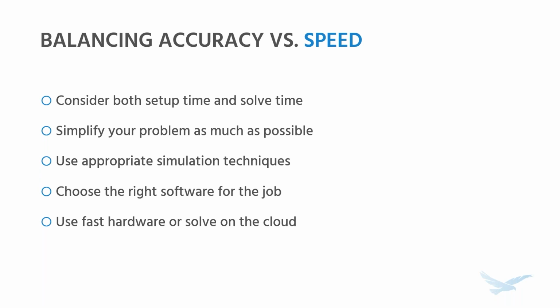And then one last one. Great question from Juan. He's asking how substantial the difference would be to use a simplification like beams or shells. Great question. And yes, those are typically great things to use. Just like using symmetry, if used appropriately, these have minimal impact on any sort of accuracy and can offer huge speed up. So definitely, if you have thin geometry or you have long, slender geometry, switching to a shell or beam mesh is a great choice.